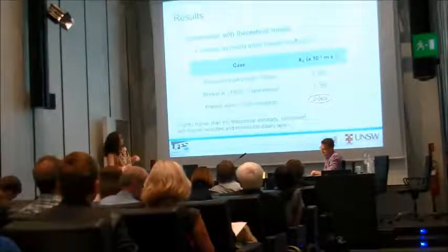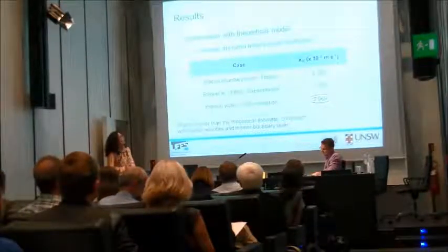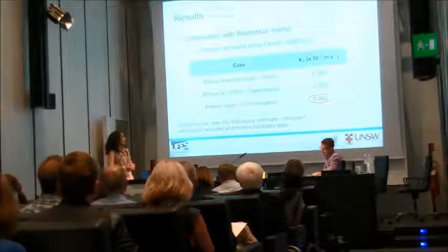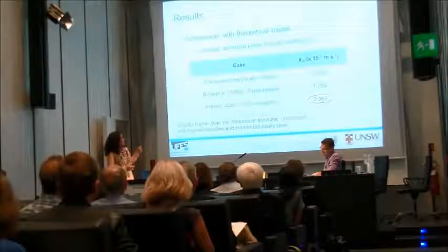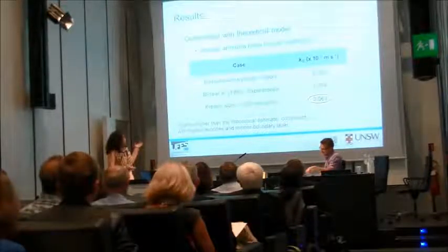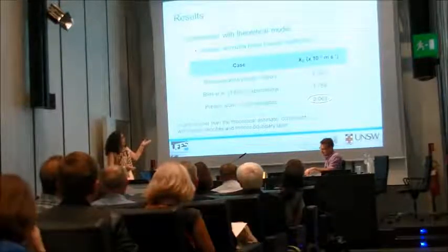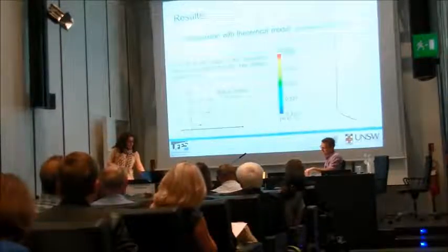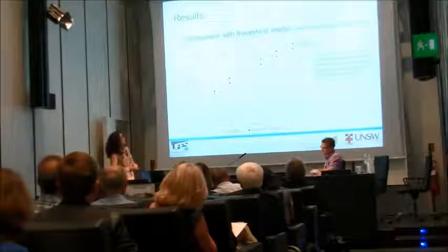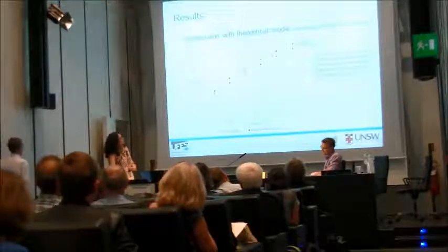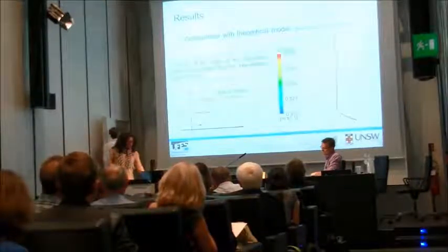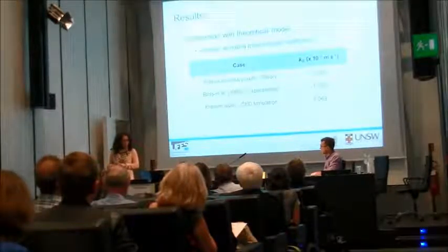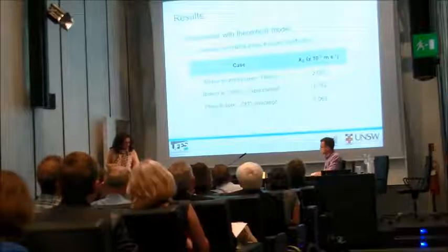And this slightly higher value of mass transfer coefficient can be explained because we got higher velocity and thinner boundary layers. I showed that before there. You see there? So it's a little bit thinner boundary layer. So that's very much consistent with the larger mass transfer coefficient.